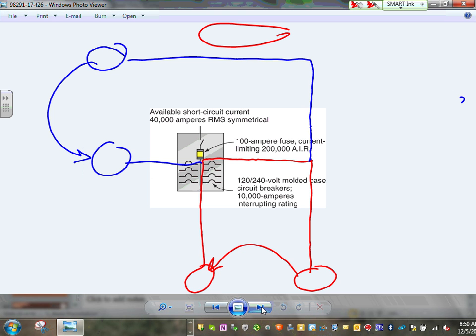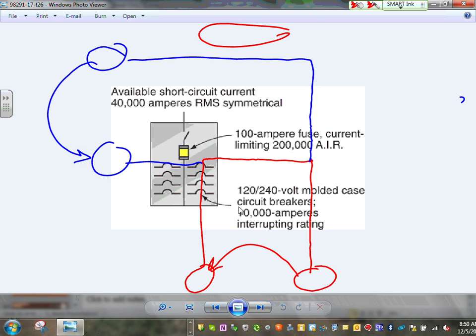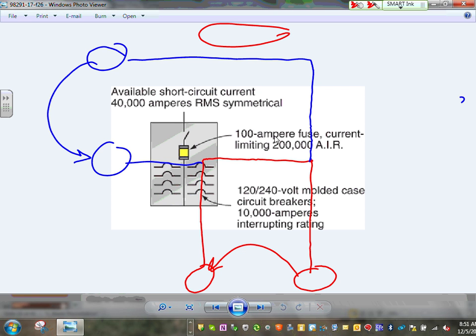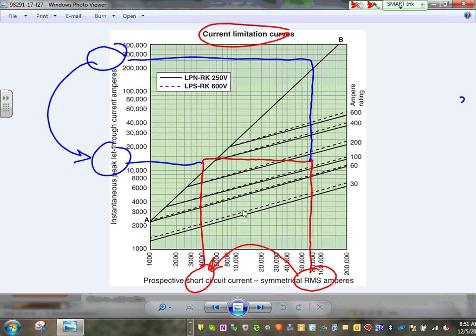That's a major concept. So this is available short circuit current and interrupting short circuit current for current limiting fuses. They can limit the current up to the current limitation, guys. Here's a 100 amp fuse, current limiting rated to 2000, so we'll limit the current that these will be exposed to, so it will not be burned. More of the low peak ones.